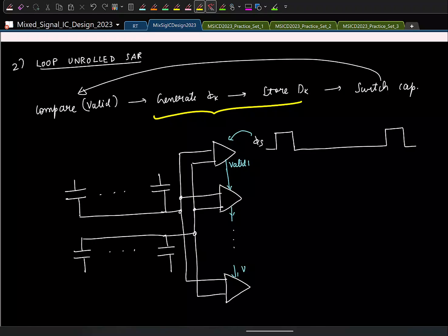So I mean, we can ask, is this really critical? This delay, is it so much? But in normal cases, no. But let us say you want to realize a really high-speed ADC, right? And in particular, let's say you want to realize a gigasamples per second ADC for serial links. There, as we saw, we have time interleaving, and usually time interleaved SAR ADCs. And at those high speeds, even a few hundreds of femtoseconds of delay is going to be a big deal.